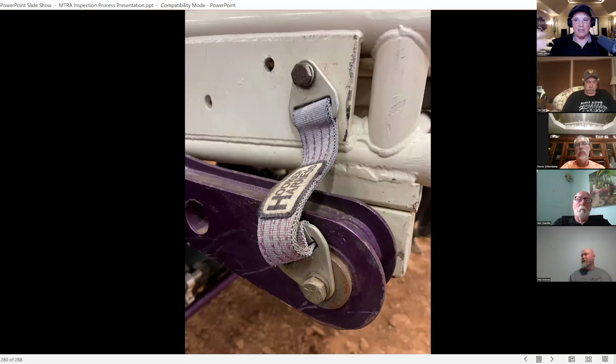We've seen many instances where the sway arms will fall and then hit the hydraulic lines and bust a hydraulic line, and you lose steering. There are multiple different things. They can damage shocks. So having this is a cheap insurance policy. It's kind of a no-brainer.